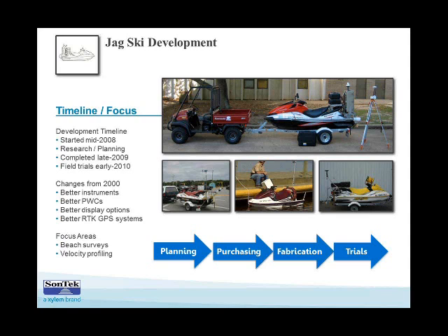And so now let's talk about after HydroSurveyor. The planning software and navigation software in HydroSurveyor is excellent for conducting bathymetric or velocity profiling studies. There is somewhat navigation support in River Surveyor Live. You can develop your own GIS shape files of your study area and plan lines and plan locations for doing CTD casting, and that's what we've done in the past. And bring those in and essentially just try and steer to that line in your display.